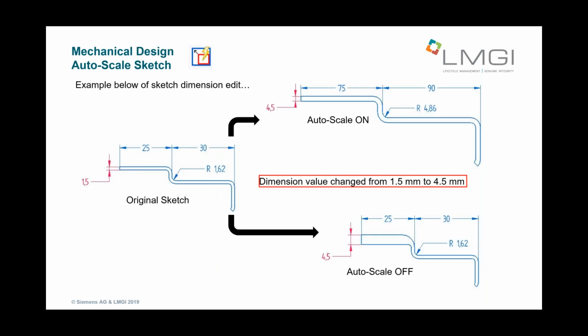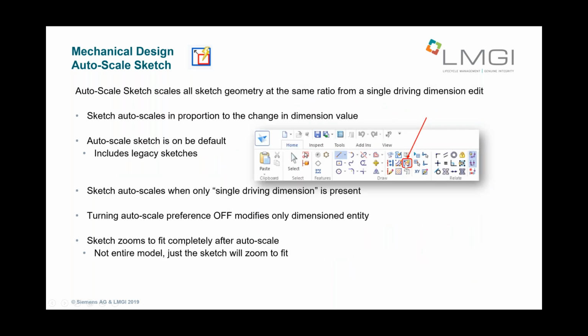This is new. This is a day-to-day time saver. If you've ever imported geometry from, let's say, an AutoCAD file or DXF or from some other system, or even if you had made a sketch and the sketch was completely out of scale, there's now a way to just auto scale the entire sketch in Solid Edge. It's a simple switch that you turn on. It comes on by default. It's right here in the draw toolbar that is depressed.